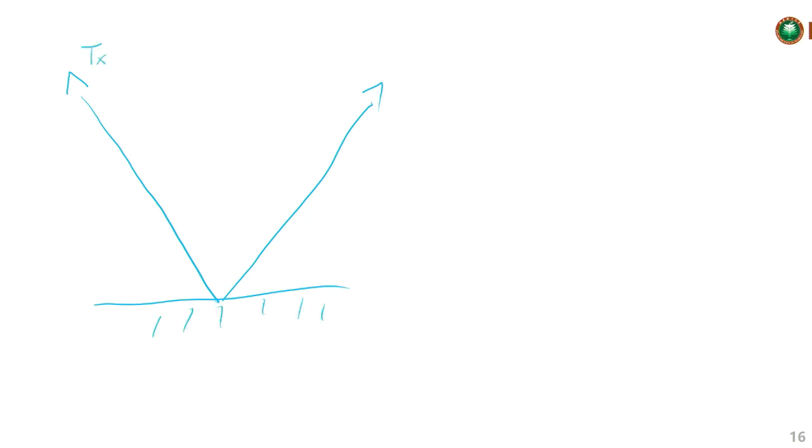All right. So another thing is for the radar systems, where we have a reflection, right? So this is the transmitter, this is the receiver, and the distance from the transmitter to the surface is R1, from the receiver to the surface is R2, for example. And the reflection loss equals 0, so that means there's no path loss due to the reflection. So it's just a specular reflection or mirror reflection.